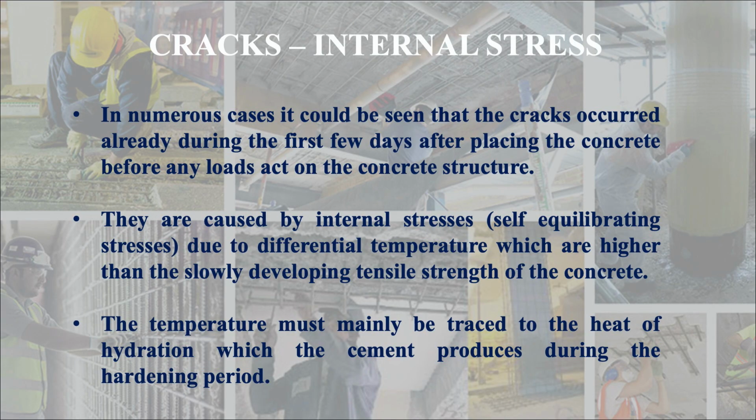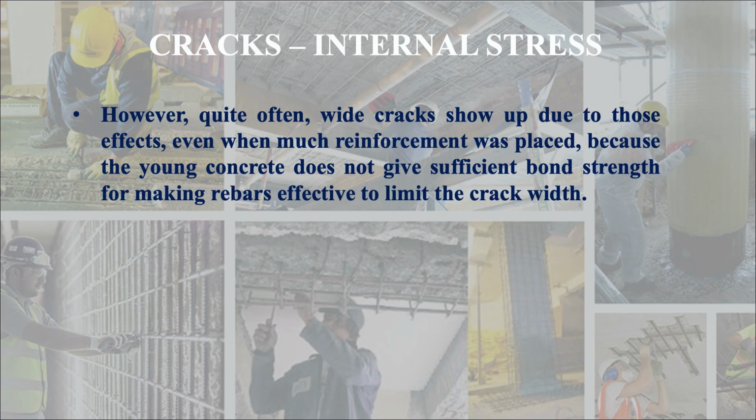The temperature must mainly be traced to the heat of hydration which the cement produces during the hardening process. However, quite often wide cracks show up due to those effects even when much reinforcement was placed, because the young concrete does not give sufficient bond strength for making reinforcing bars effective to limit the crack width.